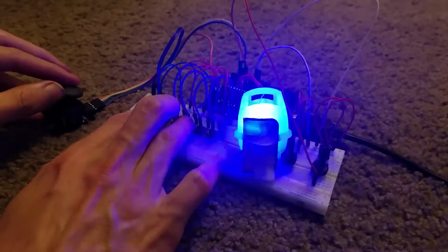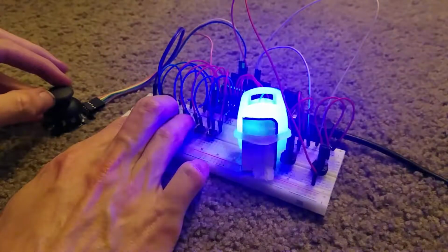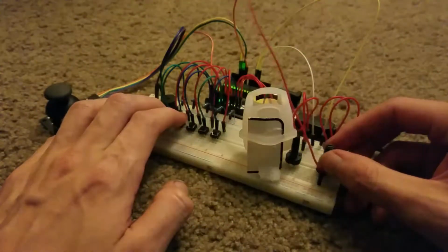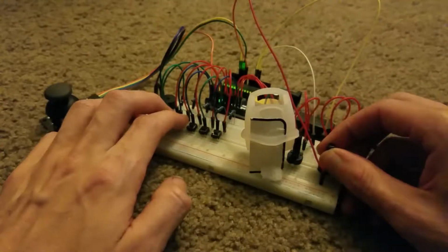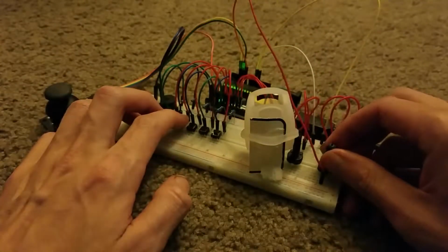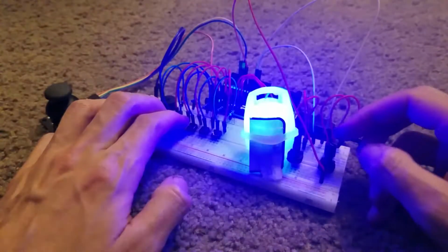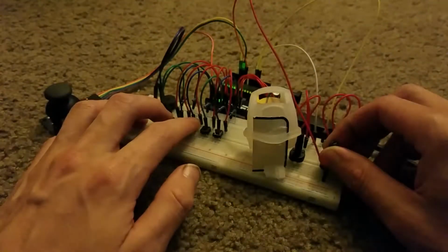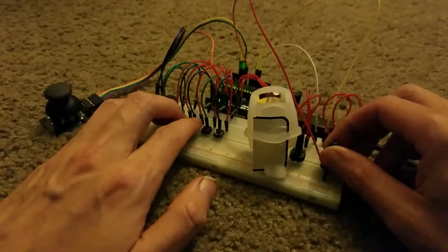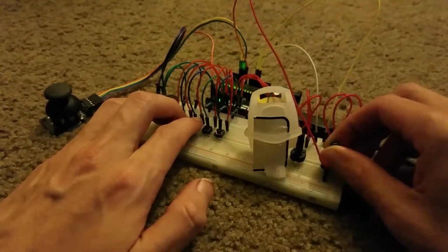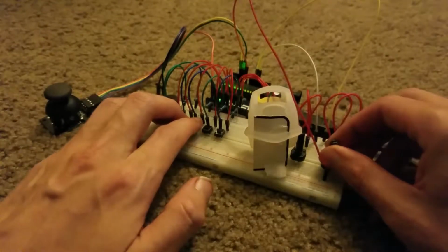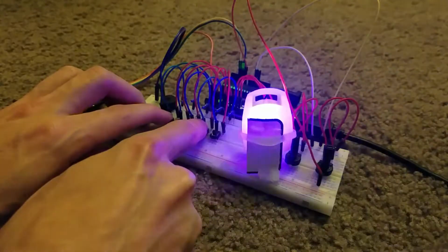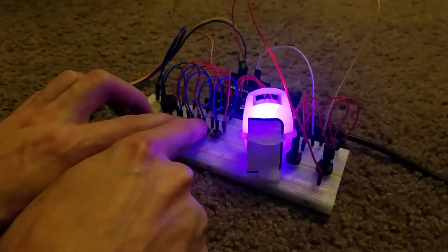Finally, we'll talk about modulating the sound and the arpeggio. Originally, I was just going to modulate the sound using pitch, but I noticed when I took away the part of the code that set my last button states to the current button states, I could just hold the note down for as long as I wanted. Then, when I divided the note timer in half on the time when it was playing the tone, while leaving the delay for the light being on still being note timer, I got a nice staccato sound. And furthermore, if I held 2 keys at once, it would run through their loop logic one by one, giving me a basic arpeggiator, so I kept it this way.